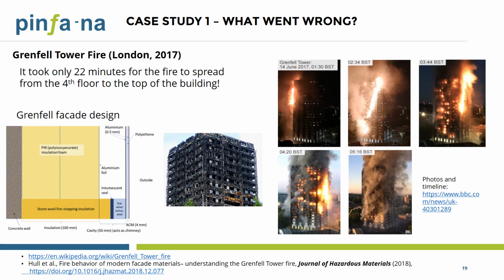The original design considered the good aesthetics and thermal insulation aspects of the facade, but it is a big failure in terms of the fire protection of the building. ACM panel has been clearly banned for use in new high-rise buildings in the UK since this accident, but that regulation should have happened earlier.